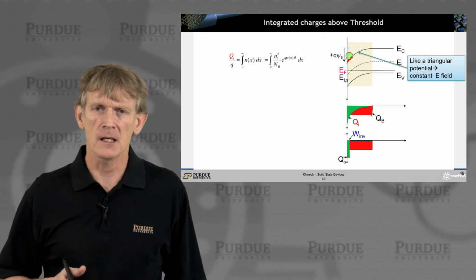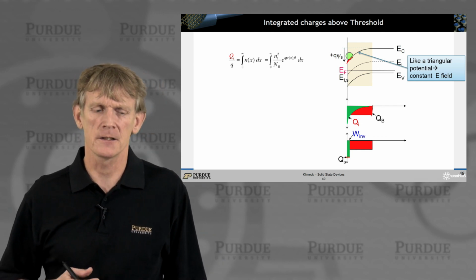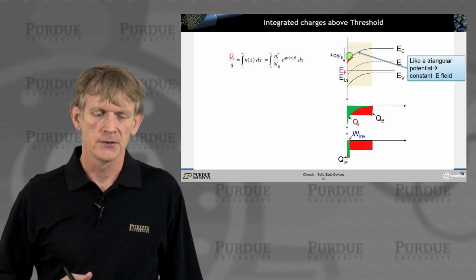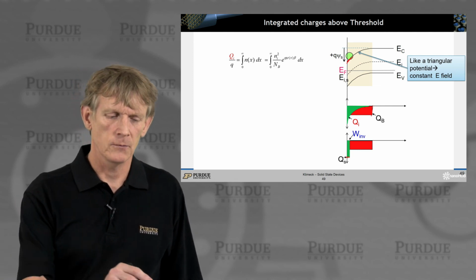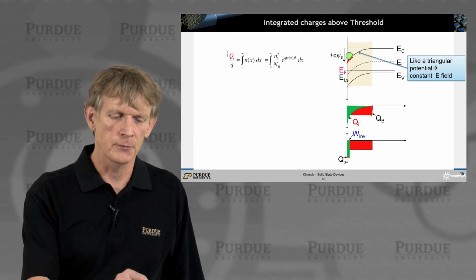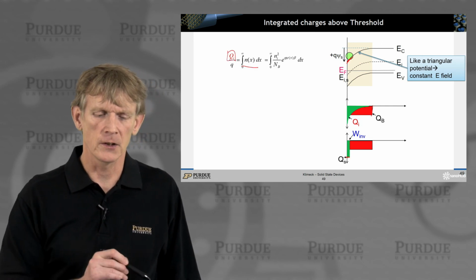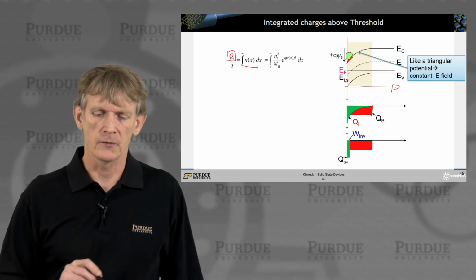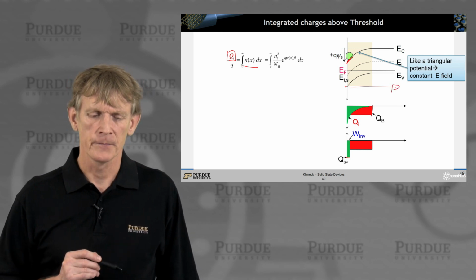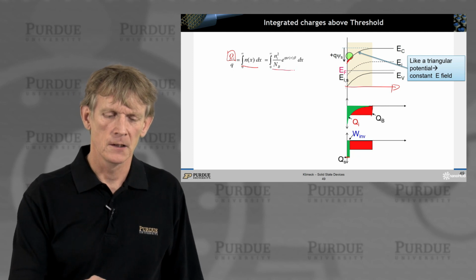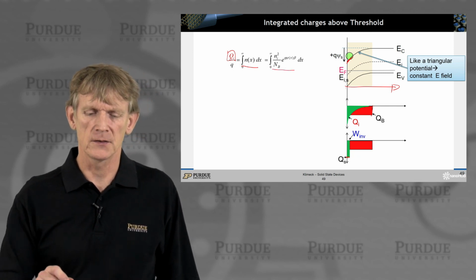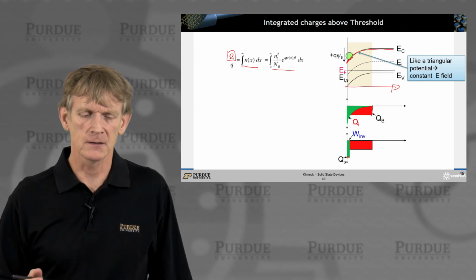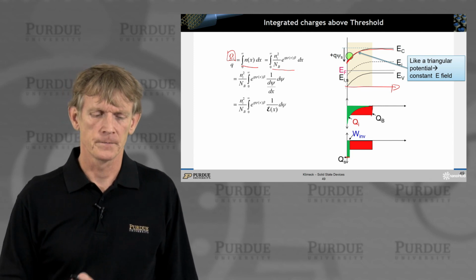All right, so let's see if we can calculate the charge in the channel above threshold, okay? So if we want to integrate or obtain the charge, we integrate over the distance x, call this distance x here, and we go from the interface to infinity, and we have an expression as a function of our psi(x), okay? Nothing new here, same expressions as what we had before.